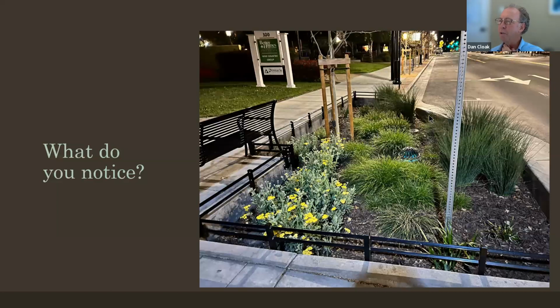Curb inlet is blocked with vegetation. Hard to see from the photo, but yeah, that could be a problem, and it might be something that they should move out of there. Are there any inflows? Yeah, the inflow. Actually, this is one of the things that you can see on here is that there's no catch basin along here. So the drainage area to this spot is likely from somewhere back behind the camera along here, along the street, at the crown of the street, over to the side, and this whole area is draining down to this point. So effective placement of the bioretention facility.